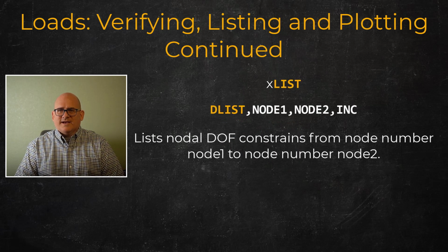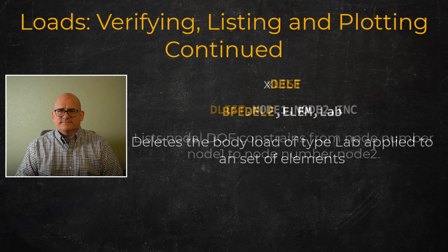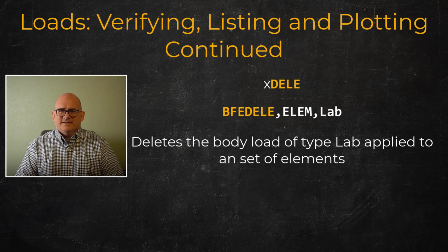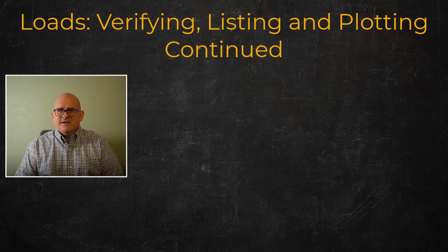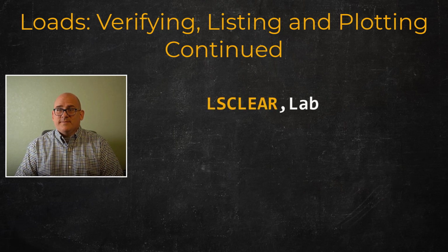Loads can be listed with the XLIST command, where X is the type of load that we saw previously. For example, the DLIST command lists the displacements and/or rotations applied to nodes. Loads can be deleted with the XDELE command. BFDELE can be used to delete the body forces applied to a set of elements. Deleting loads from a solid model automatically deletes the load from the finite element model if the load has been transferred, but the opposite is not true. All loads can be deleted at once with the LSCLEAR,ALL command.